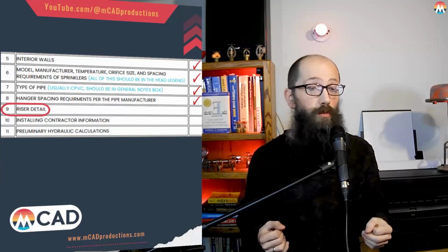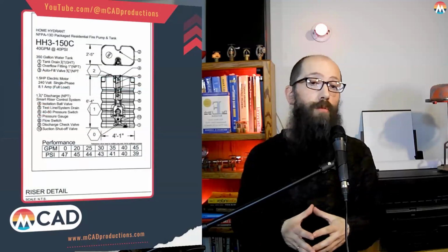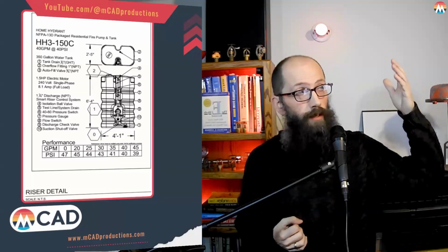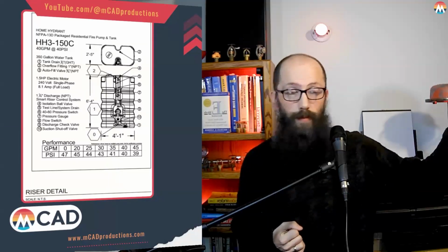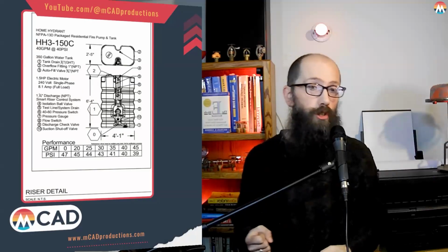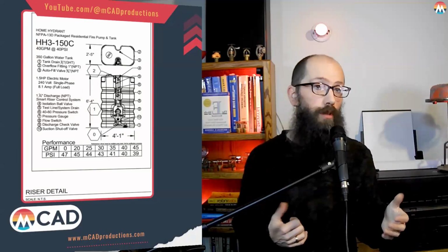Okay, so the next thing is riser detail. On our project that we did, we used this home hydrant, and this is our riser detail. This pipe that's in the center of that tank on the drawing there is our riser assembly.